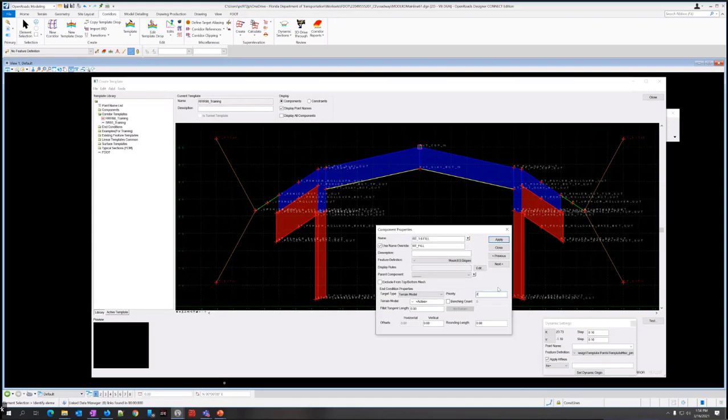All right, so we're on step 5 here. We're changing the priority value. So we change this to 2. What this is doing is, in this end condition, when there's 2 of them, if you don't have different priorities, it's actually going to create a conflict because it doesn't know which one to do. So by setting this to 2 and this cut is set to 1, the fill is set to 2. It's going to try the number 1 first. So it'll try doing that cut, and then because it's infinite, it'll just draw this line until,